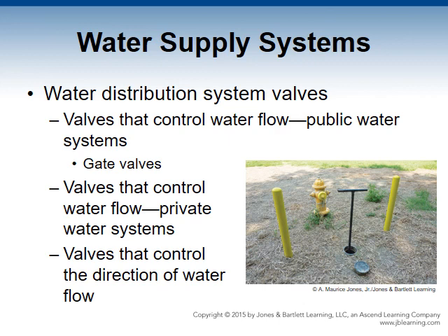Another indicator is a wall post indicator valve. It is used in situations where it is impossible or impractical to install a freestanding PIV. Yet, the requirements for some type of indicating valves remain. Mechanically, the wall post indicating valve is similar to the post indicating valve, but instead of sticking out of the ground, it is mounted on the side of a building, with a valve stem feeding through the wall.